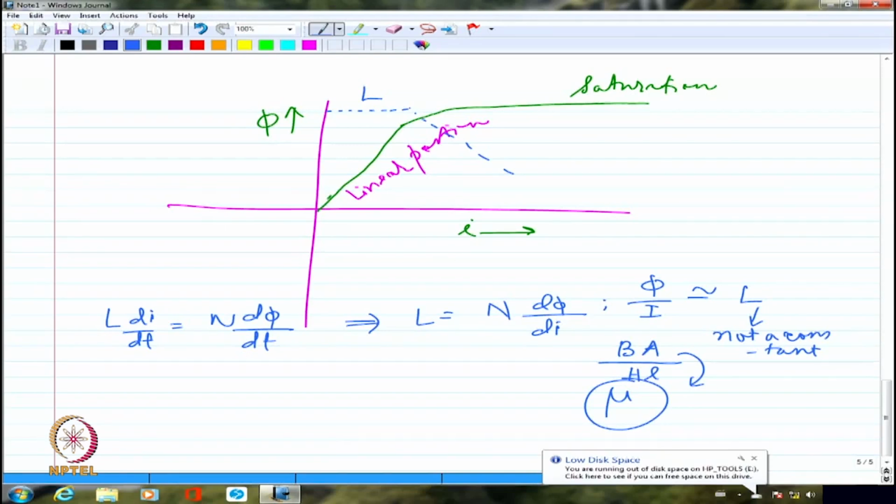But we are constrained by the fact that iron is going to give me more magnetic flux for a given current, so we are bound to use that. So that's all the more reason we should take a look at what happens when this nonlinear behavior creeps into the magnetization characteristics. Okay, so we will just recall the current ring theory of magnetism.